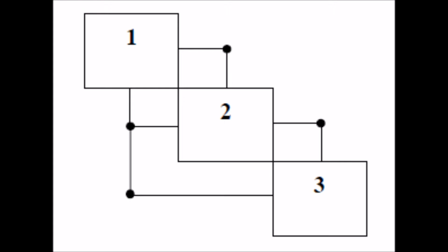It is apparent that subsystem 1 provides a propellant flow at a designated flow rate that is injected into subsystem 2. This increases the pressure within the discharge chamber, or subsystem 2, which is fed back into subsystem 1 as a method to determine choked flow. This is the point where flow rate is maximized and ideal nozzle equations of a thruster can be utilized.